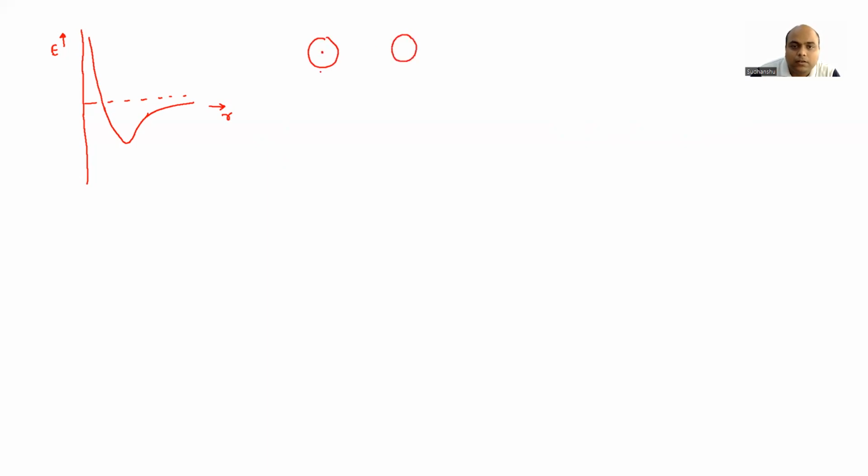So this is the similarity with the spring of this atomic structure. Let me just show you a schematic very quickly about the energy versus R. In the y-axis you have energy, and in the x-axis you have distance, right? So what I am talking about here is, you have two atoms and this distance is R naught. Okay. So this is in equilibrium condition. That means the energy has to be minimum, and that means this distance here is your R naught. So there is no force, okay, and energy is minimum.